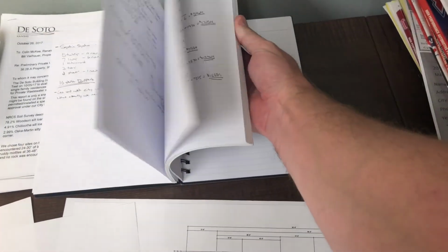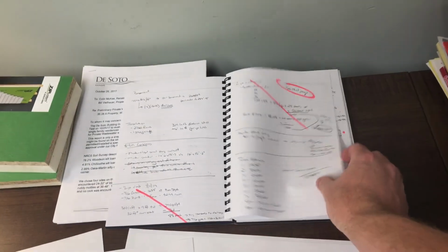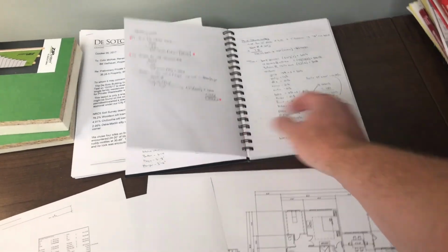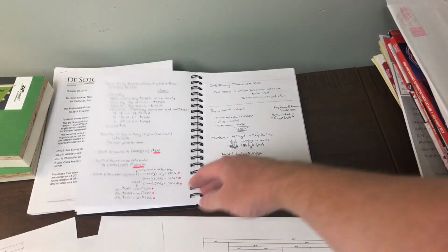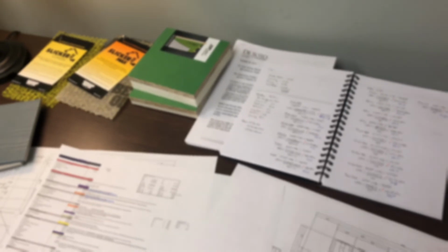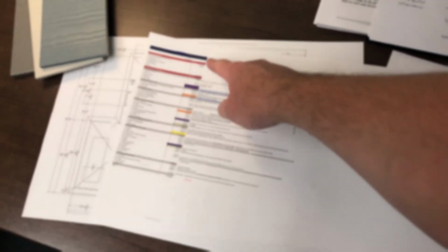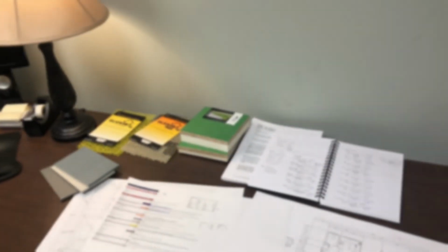Now a lot of these are ballpark quotes. Some of them are just rule of thumb quotes, but I got it all. This entire notebook here is full of nothing but calling people and getting quotes for the basement, exterior sheathing, insulation, cabinets, siding material, foundation waterproofing, silt fence, carpet, just anything and everything. I figured out how many square feet I needed of, say, carpet or drywall, sent those all out for quotes, and filled in this little sheet right here. That got me a rough budget of what it's going to cost to build this house and a cost per square foot, because I know how many square feet it is.